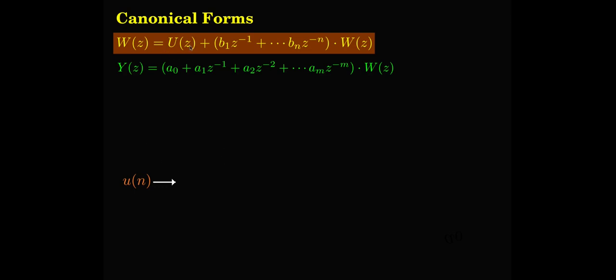So U(z), which I am going to put as u(n), goes into a summer, a summing block, where this whole thing plus u(n) gets added up. All these terms can be obtained by using delay blocks. So let me say that there is a w(n), which represents the n domain value of the z transformed variable W(z). Let me put some unit delay terms here, z to the power of minus 1.